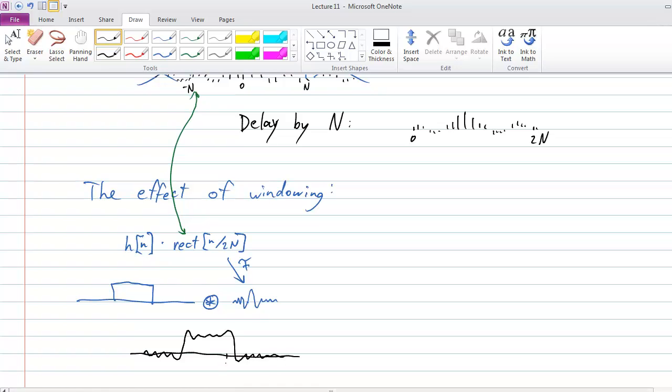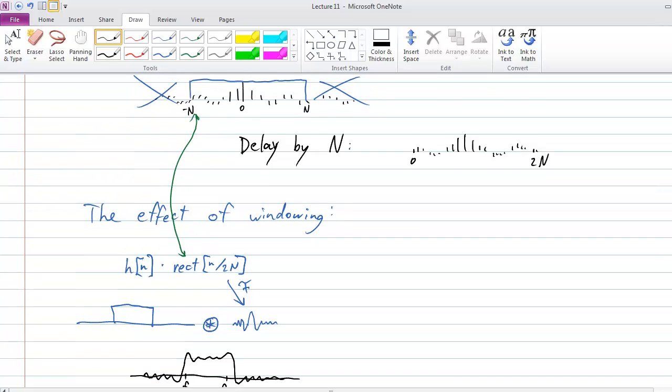And there's our cutoff frequency from before. So by changing our low-pass filter to cut off the ends of it, something you might do without even thinking about it in MATLAB, you might say, oh, I'm going to apply some filter, but I can only have finite length vectors, so I'm just going to cut off the ends. Well, now we know what that actually is doing to your filter.